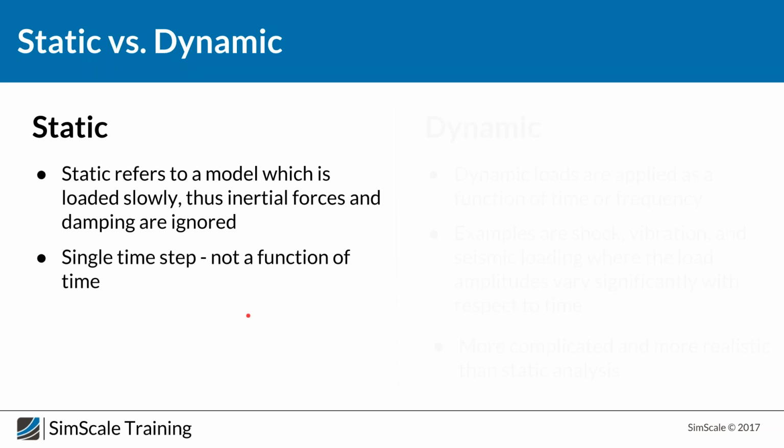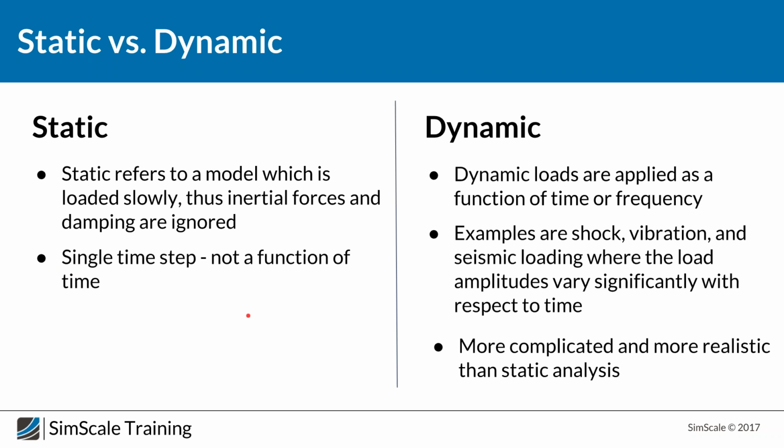In contrast to that, in dynamic simulations we really have a physical time, which means we have no limitations. Loads can be dynamic, a function of time or of frequency, and can be added very rapidly. Very good examples are shocks, vibration, and seismic loading, where the load amplitude varies significantly with respect to time, and where I really need dynamic simulation because these dynamic effects also change the physics.